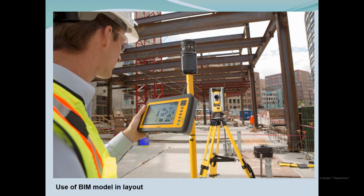The surveyor taps the personal computer screen to indicate the building component to be located, and the total station directs the rover to the point. The technology allows the surveyors to set and save new points in relation to the design BIM model.